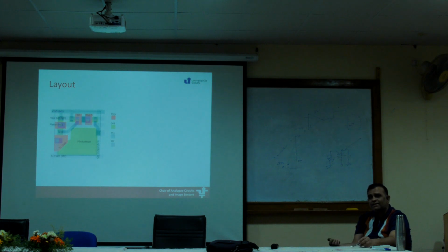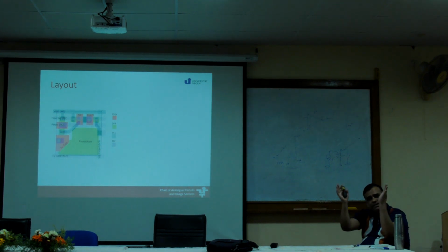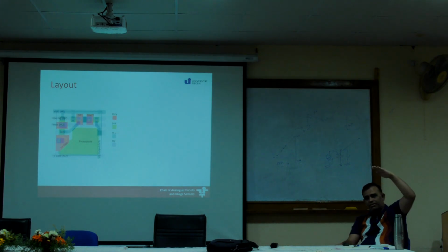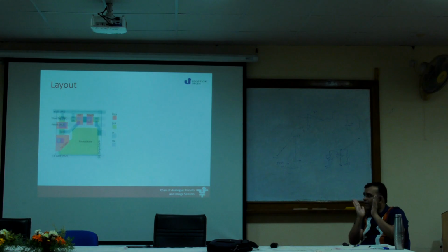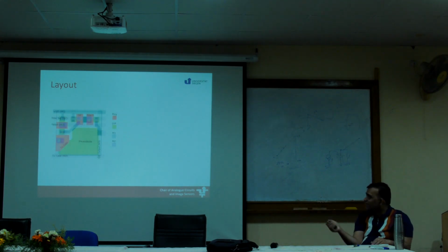There are some other tricks which we apply here. We know lenses can help us point the light. So in many of the advanced cameras, we have a big lens on top, but then we have a tiny micro lens sitting on top of each pixel. And the role of this micro lens, since the pixel has quite a lot of non-useful area, is to direct light straight onto the photosensitive diode.